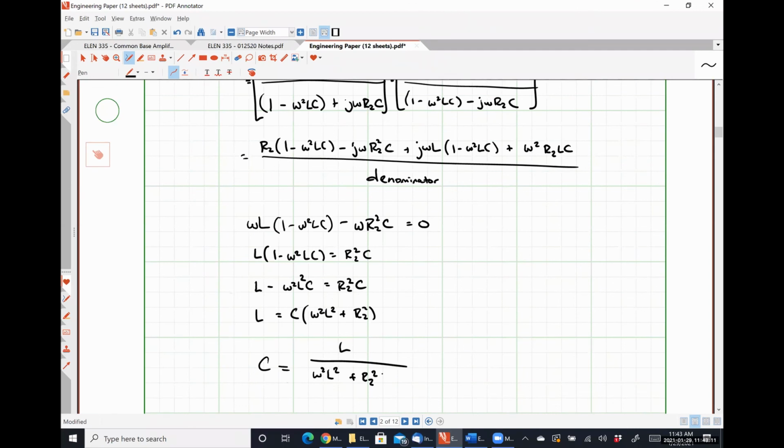And that will be the value of the capacitor that makes my system behave as if it sees a purely real impedance. That's kind of fundamental to an impedance matching network, which you'll probably talk about to some extent next year. It's ways to make loads look like different things so that when you connect it to a particular source or measurement circuit, you don't get weird losses and resonances and stuff like that. Anyhow, does that fairly answer your question? All right. How can I help you?